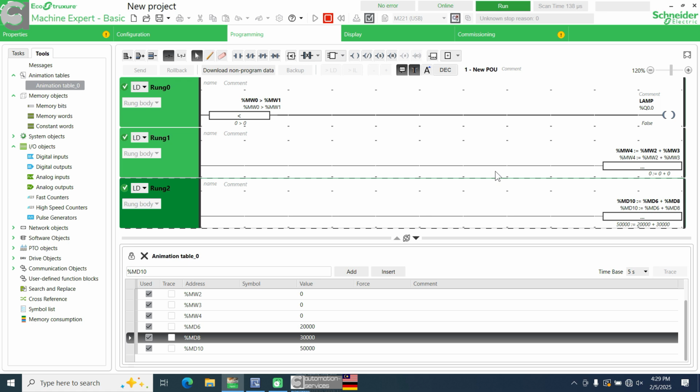So as a programmer, we do the calculation, convert to Celsius. Once the PLC reads the current Celsius and your set point, it has not yet reached, so the PLC will turn on your heating coil. So it starts working.